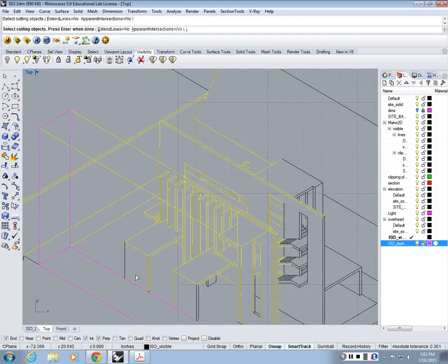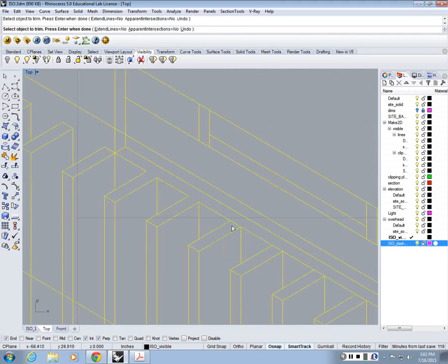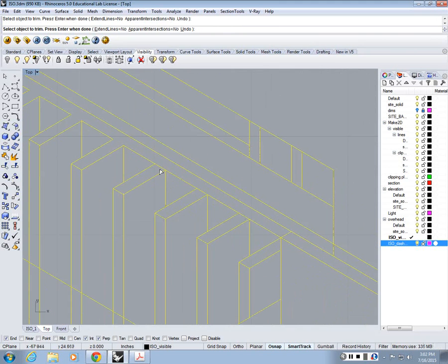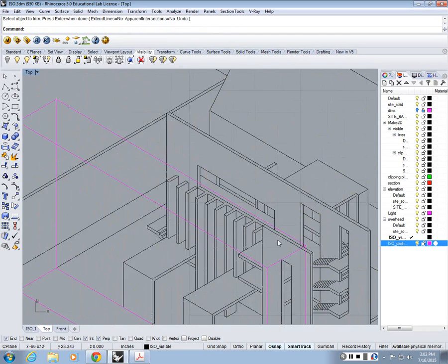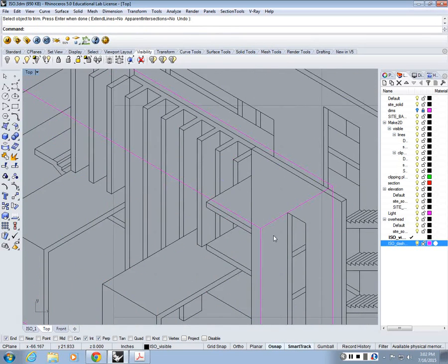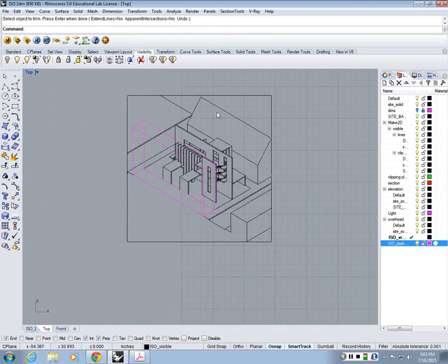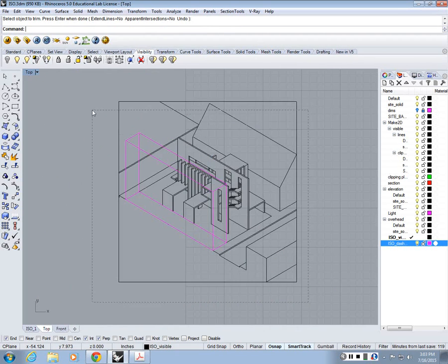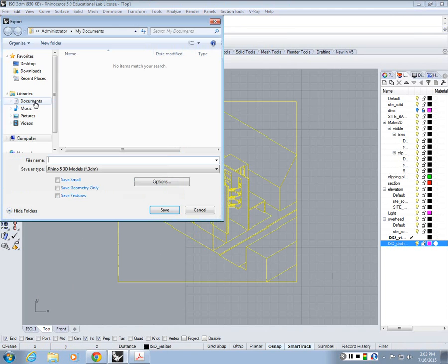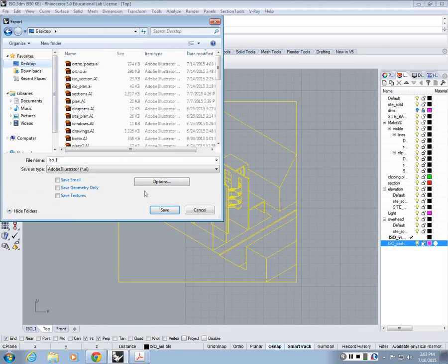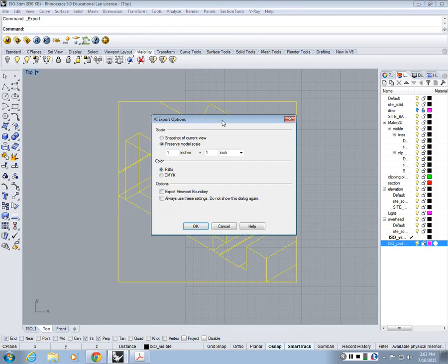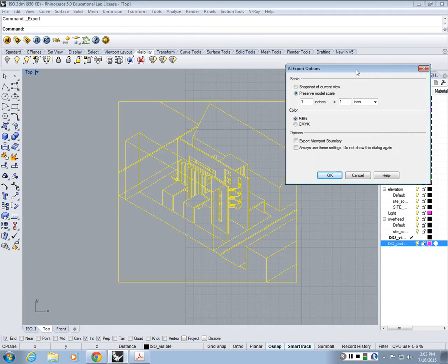And let's do it here too. Alright, so I'm going to export once this drawing is ready. You're going to choose it, export selected, Adobe Illustrator, ISO 1, save. And this is the conversion. It's 1:1 because we already drafted it into 23 inches, right? So when we open in Illustrator, we want it to fit to the artboard perfectly.